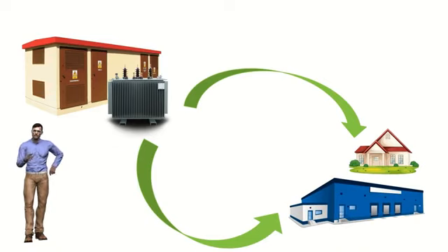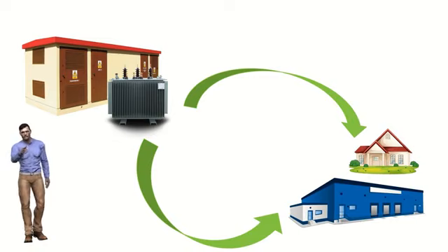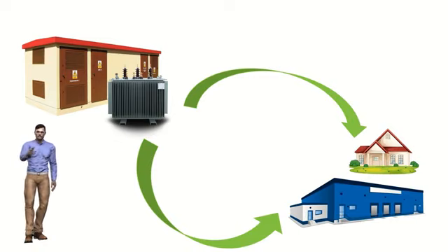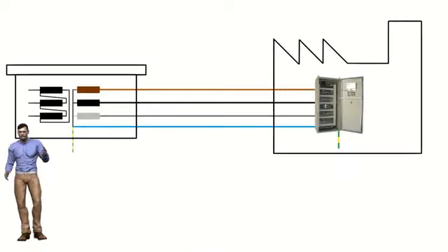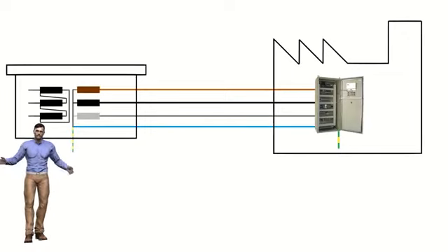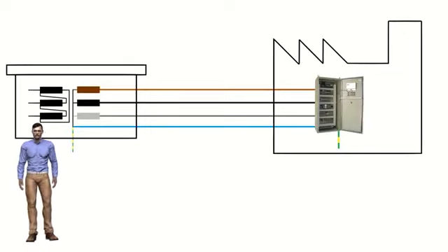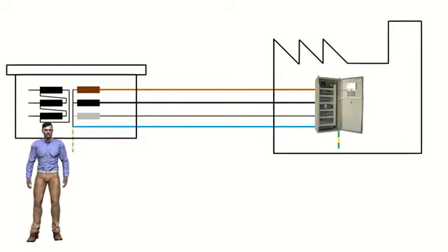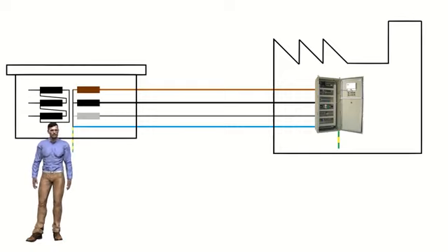In these transformation centers, a transformer reduces the voltage from, for example 30 kilovolts, to the 400 volts AC that we have mentioned. From the transformation center, the electrical energy will be transported to the users through three-phase lines made up of 3 cables for each of the 3 phases, and an additional neutral cable so that we will be able to supply three-phase loads such as motors, or single-phase such as computers.